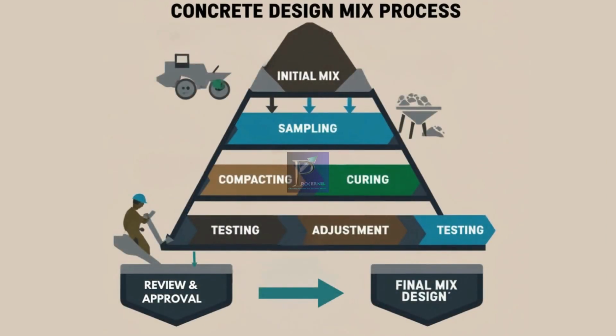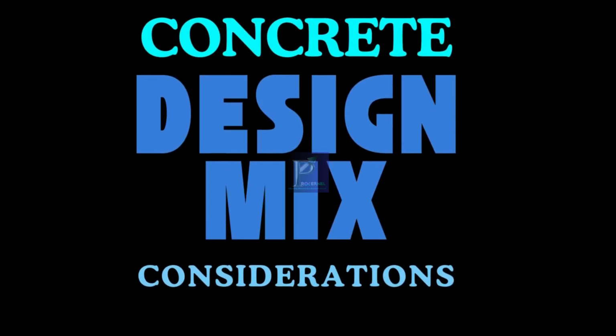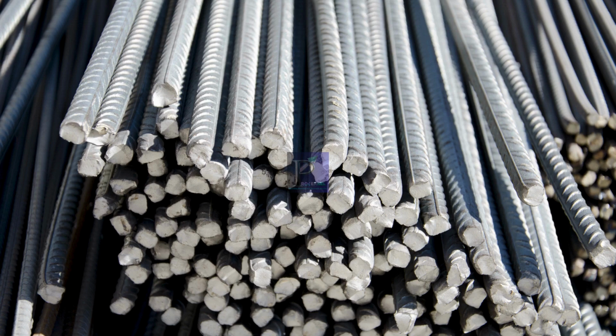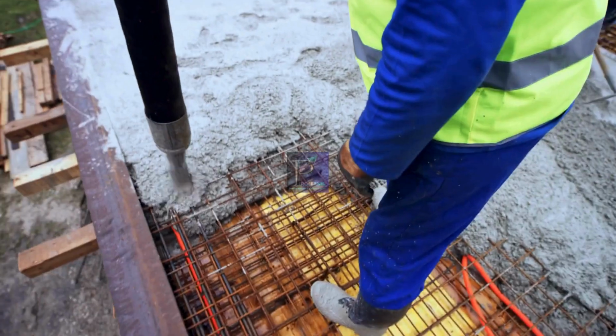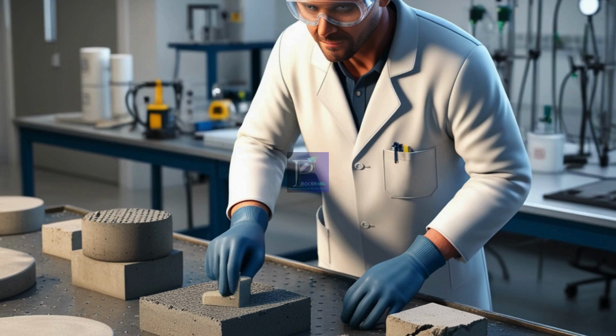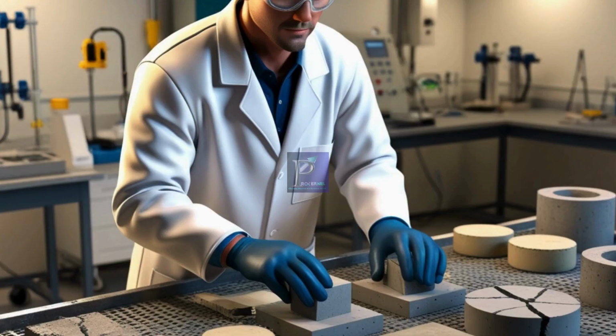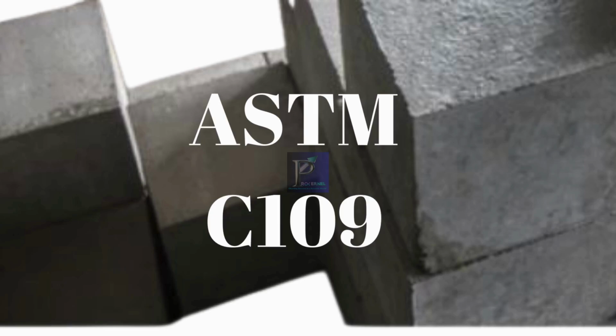Let's understand now about the design mix considerations as per IS 10262. Selection of grade. The approval of the design mix is based on the concrete grade. Grade differs for each material. For example, grade of steel indicates the specific properties and composition of a steel alloy. Similarly, cement grade. For instance, 33 grade cement achieves a compressive strength of 33 newtons per mm square, which is inadequate for higher structures. You can refer to ASTM C109, compressive strength of hydraulic cement mortars, for more information.